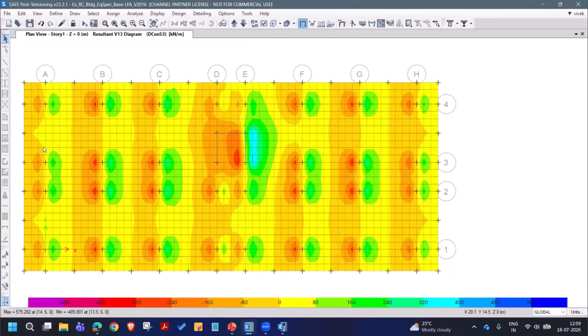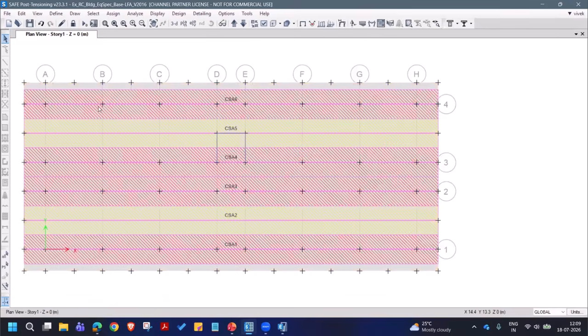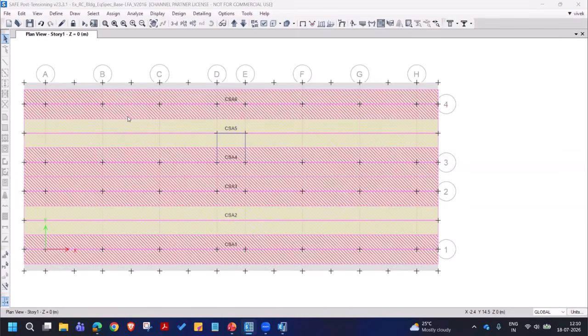Right. So in this model, I kept it very simple, covering the basics. But here to the columns, you can add the stiff area element to model the junction, to improve the behavior as well as the force distribution. Okay. Now I'll jump to another example where I will discuss a few more things in detail.